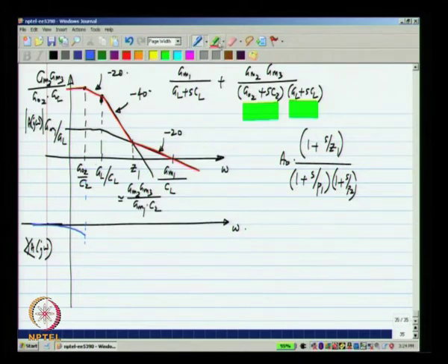The second pole will add another 45 degrees phase at the frequency of the pole, and then the phase shift due to that pole also saturates to minus 90. So, after you pass these two poles, what happens is the phase would shift to minus 180 degrees,